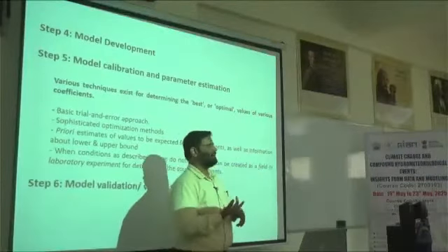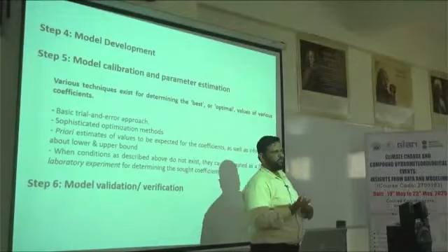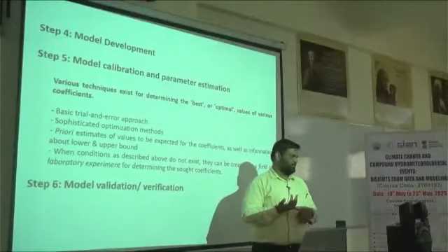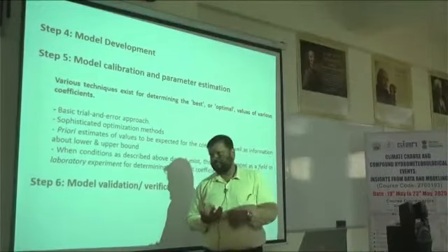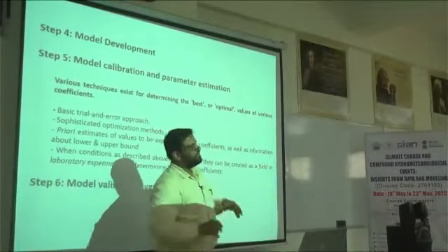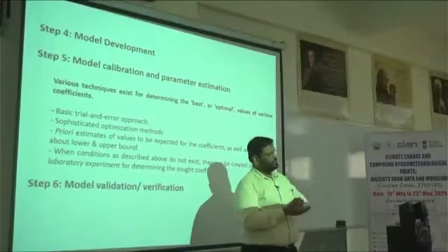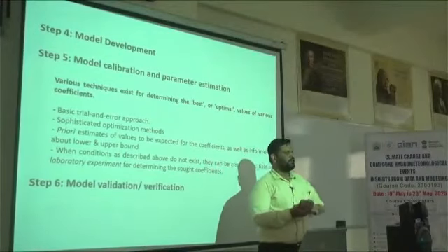Then the third one is the Hargreaves equation. In that equation you require only solar radiation values and minimum and maximum temperatures. Based on solar radiation and minimum and maximum temperature values only, it will give the evaporation values. So like that, if you have the knowledge of hydrology, then only you will be able to do such kind of analysis.